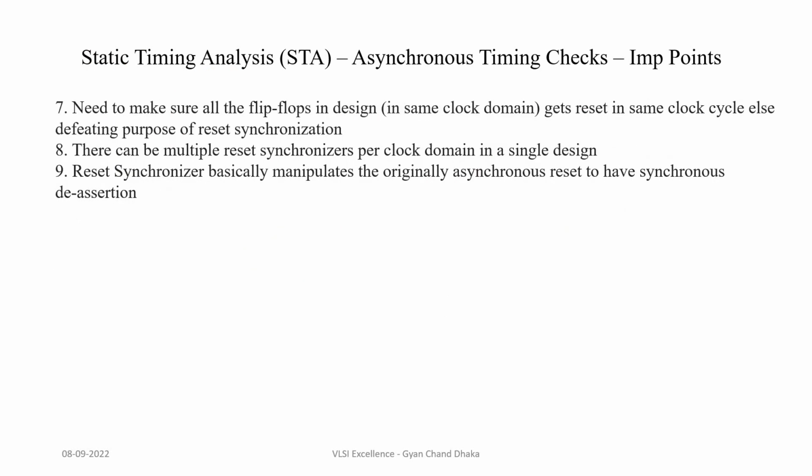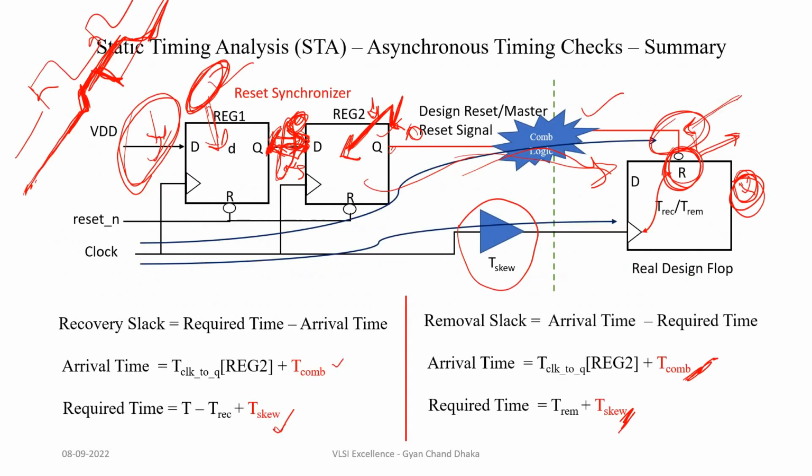Also, we have to make sure that all the flip-flops in the design get reset in the same clock cycle. That means whenever the reset signal is launched by this flip-flop, it should reach all the flip-flops in our design in one clock cycle. Otherwise, the purpose of reset synchronization doesn't make any sense.